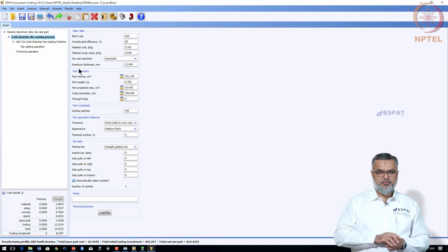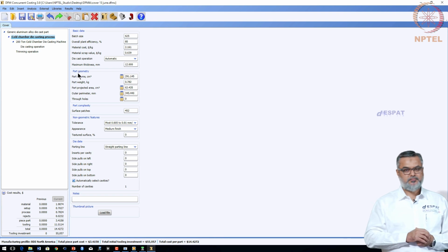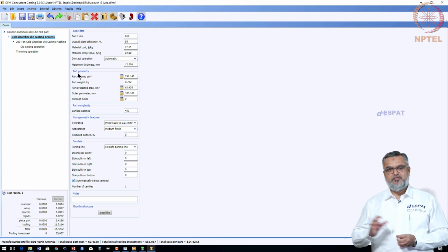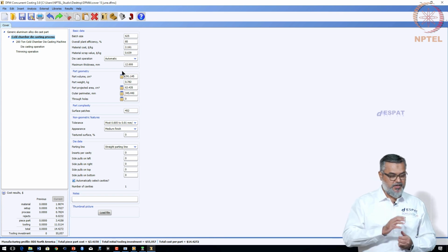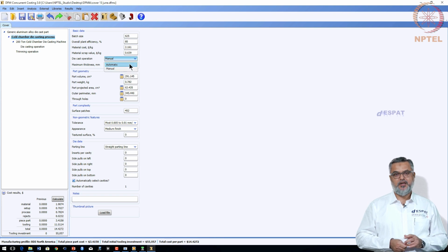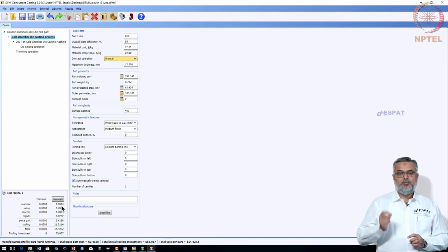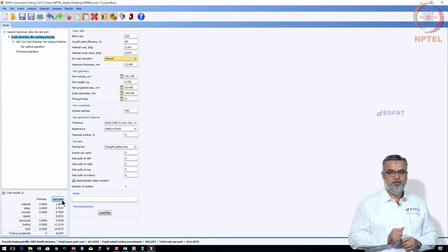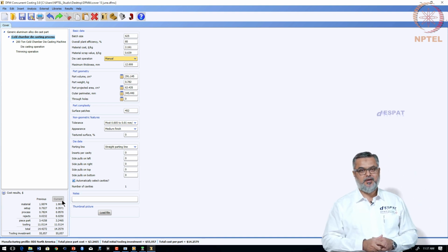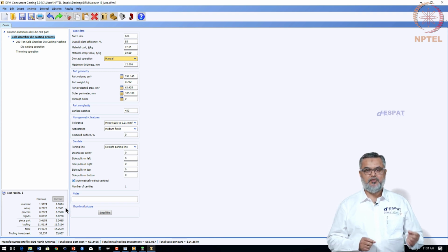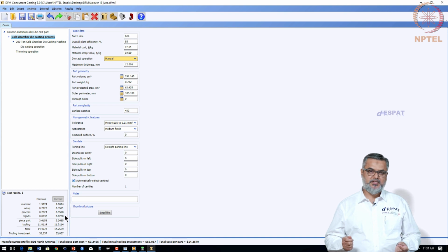details of all these process charts, but we have said that DFMA gives you a rapid feedback of your design intent. For example, if I have a process here and let us say in my setup I do not have automatic, but it is manual, what is going to be the implication of this? I select the option, I press this calculate button under the cost window, and what I get is a comparison of what my current design and what my previous design is.